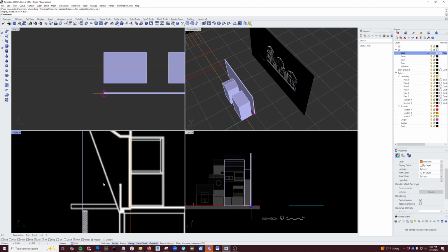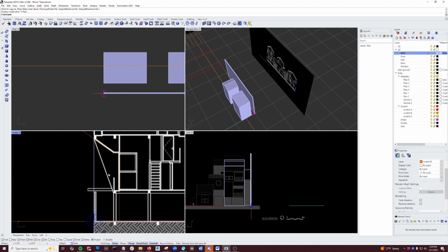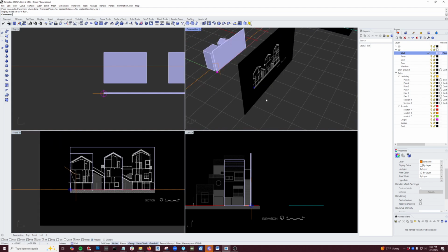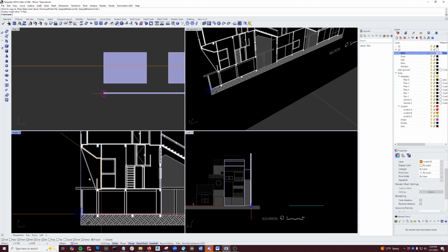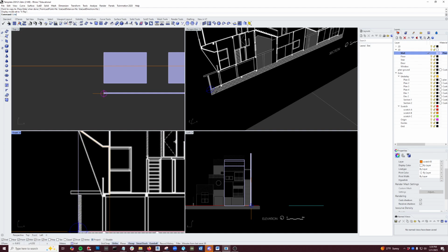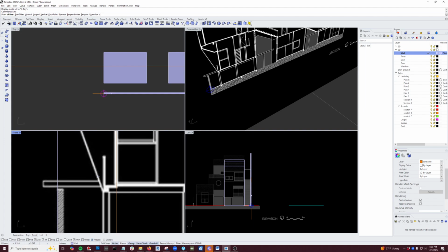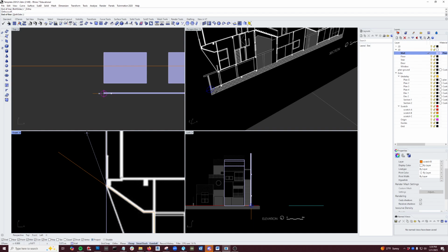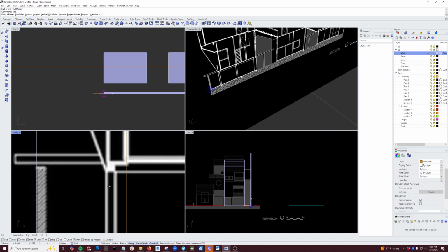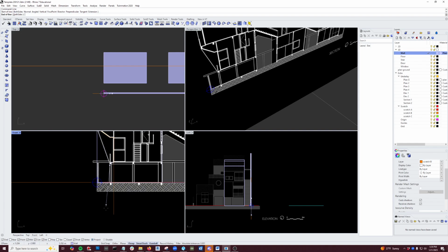And then what's the profile? Well, you can see in this section that we lined up, that's this section, right here. That's the line that's talking about the profile of the building over here. So let's just trace that. We'll do it a little roughly. I'm going to turn off ortho, F8, and then come back here. I'm going to turn ortho back on.